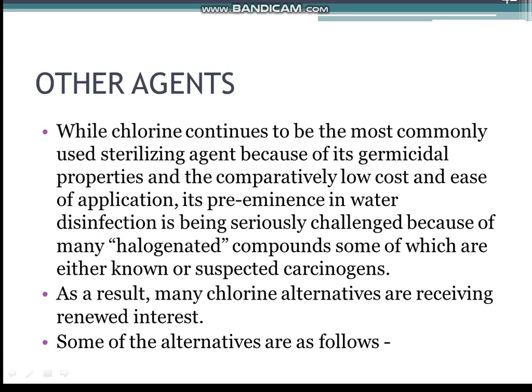Moving on to other agents. What are different kinds of other agents that we can use for disinfection? While chlorine continues to be the most commonly used sterilizing agent because of its germicidal properties and the comparatively low cost and ease of application, its preeminence in water disinfection is being seriously challenged because of the discovery that chlorination of water can lead to the formation of many halogenated compounds, some of which are either known or suspected carcinogens.